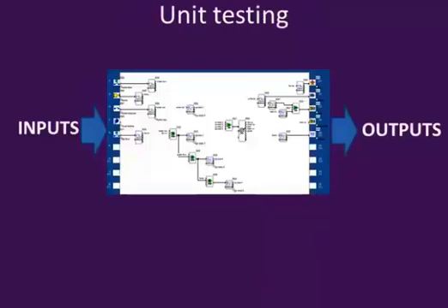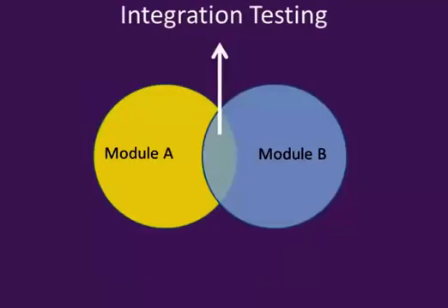Unit testing. A unit is the smallest component. In our case, that's usually the individual PLC. You test it to see if the code works. Integration testing involves building the entire system and checking it. Most control systems involve more than one PLC networked together and probably a SCADA on top of that.